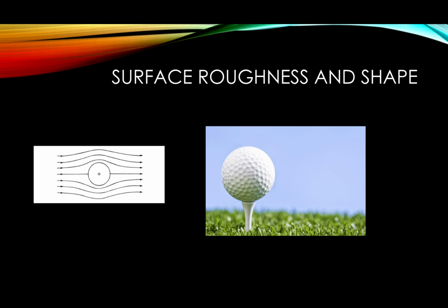Changing the surface roughness of an object to improve its aerodynamic performance can best be seen in the game of golf. The ball has been designed with dimples all over the surface of the sphere, which helps keep the boundary layer attached and results in less drag on the ball. Our cylinder had trip strips attached on one location of the cylinder. This asymmetry likely yields less boundary layer reattachment. There is a limit with surface roughness where the object becomes so rough that the flow over the object becomes turbulent from the onset and the drag is increased.